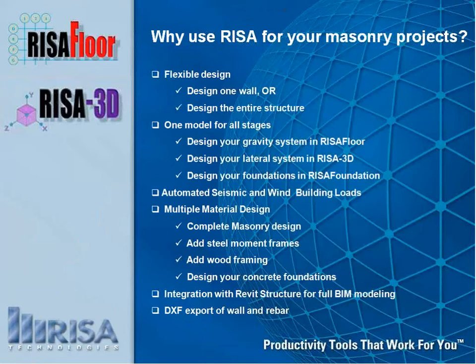Also, we have one model for all the stages of the project. That's really important because you can do your design of your gravity system in RISA Floor and take the same model that you just built directly into RISA 3D to do the lateral system. When you're finished with the lateral system, you can take that one model directly into RISA Foundation to do the design for both the gravity and the lateral forces for your foundation. So giving you the power of that one model means that you can just build it just once.